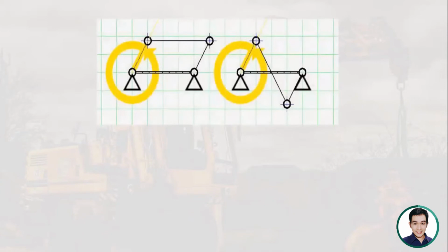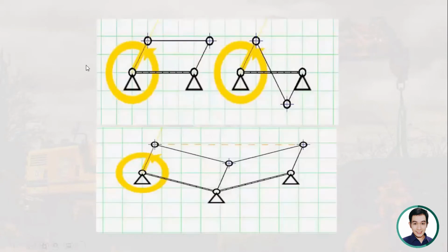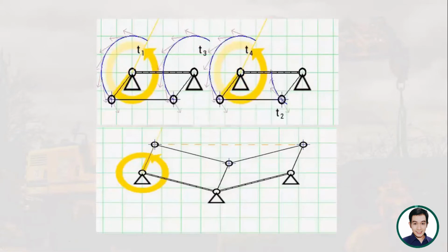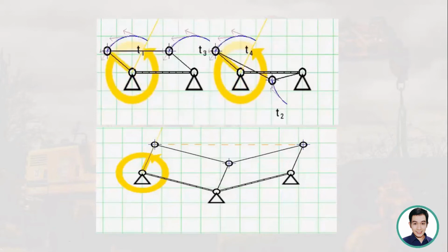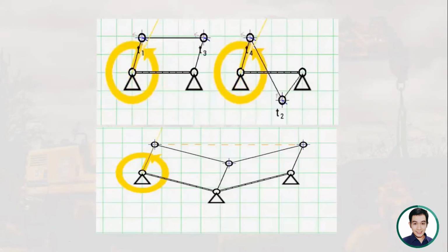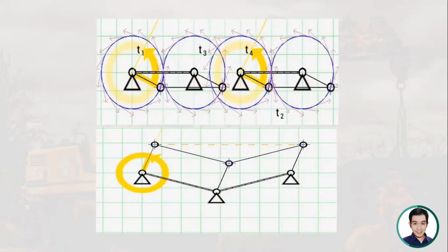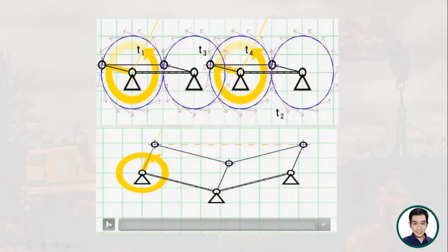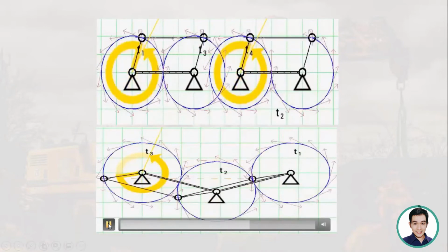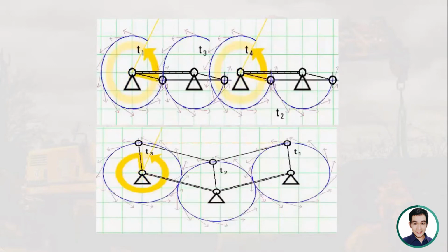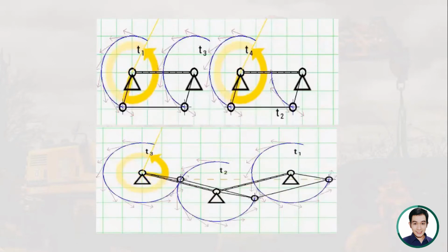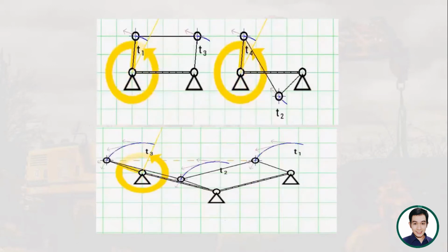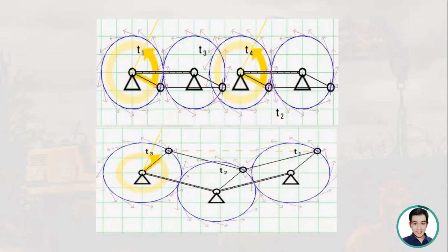So you can see here in this example, we have a special case Grashof. We have a parallelogram special case Grashof, which experiences a change point, wherein at every two revolutions, it changes its motion. And another one, you can see that it rotates, then it stops, then it changes again. So that's why we have here the change point. That happens when we have a special Grashof case.